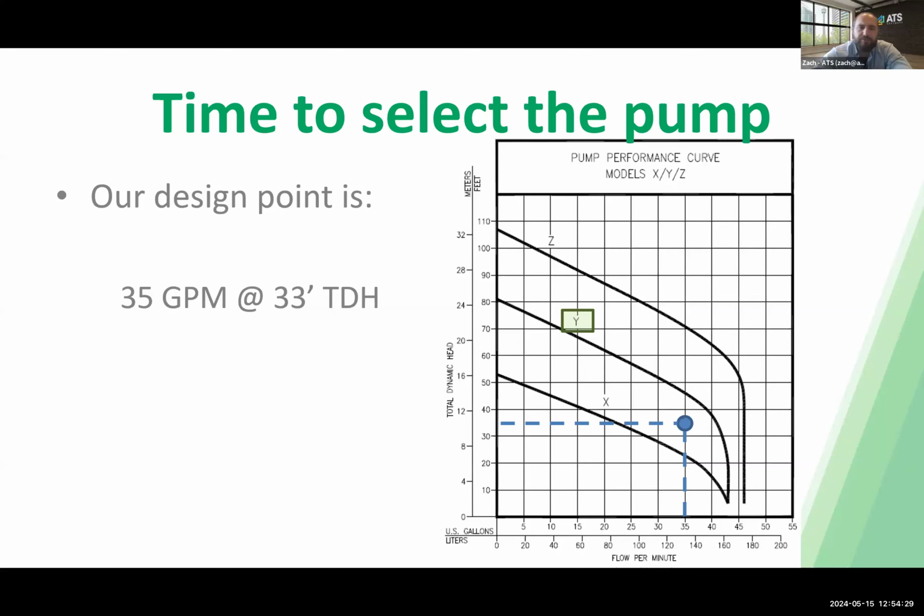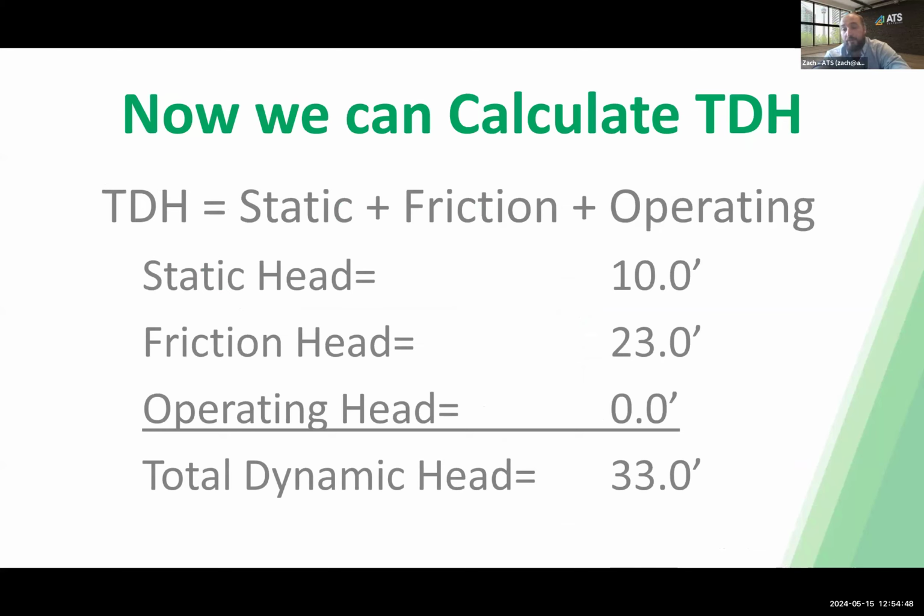Okay. And then a couple of real quick ones I'll knock off as we go. Does the static head have anything to do with the pump performance curve? As we just covered, the static head adds to your friction loss head and your operating head in order to get that design point. And then, more details on the operating head: that would be the pressure at your delivery of the water, if you're not going to gravity and you have to overcome an operating pressure. That's when it is included, and it would just be added to your combination there. Yes.